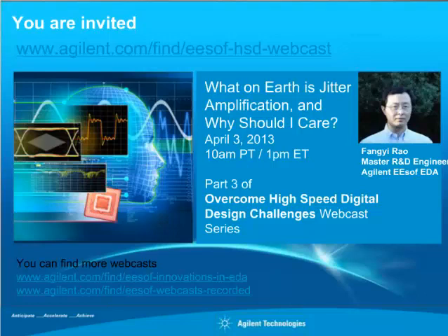It has to be ADS 2012 or afterwards, and we use the same component for the electrical redriver as the optical redriver, and the only difference is you're loading an electrical to electrical model into that component using the .ibis file. So the symbols are identical to the electrical redriver. It's just that you're loading a different model, and internally the EO and OE processing is internal to the model. So as far as ADS is concerned, it's electrical in and electrical out. And the opto is kind of baked into the center of the model.